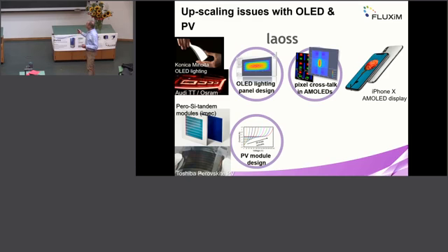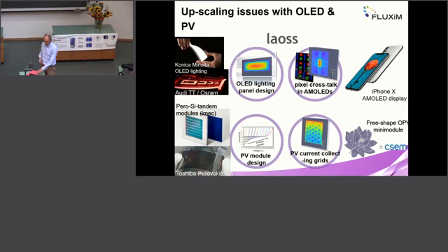This example shows JV curves for a fixed total size of PV, but you can vary the number of cells you connect in series for the given total size, and then you can have all kinds of JV curves, more voltage or more current, depending on the splitting into cells. But these are examples that you will see more info on later.